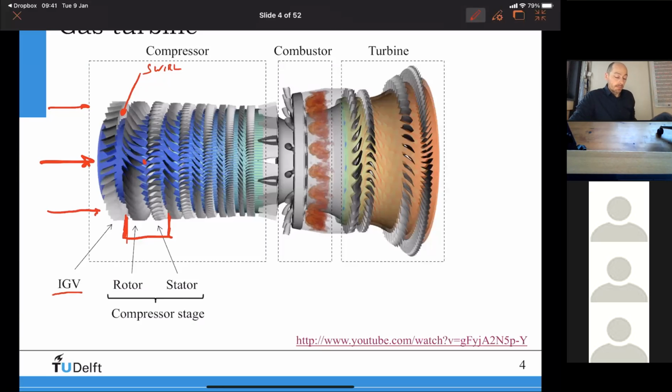So you have added some work in order to turn the flow. Because of this turning of the flow, in the stator you are able to make the flow straight again, but by making it straight, you increase the pressure. As I said in the previous lectures, a compressor basically consists of two sections of diffusers. A diffuser is something like that. One rotates, and the other diffuser part is stationary and is called a stator. So you have first the rotor and then the stator.